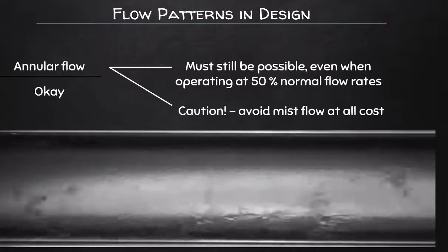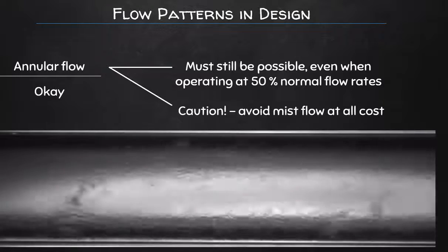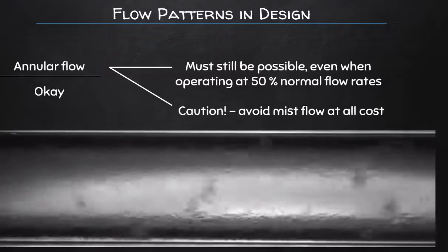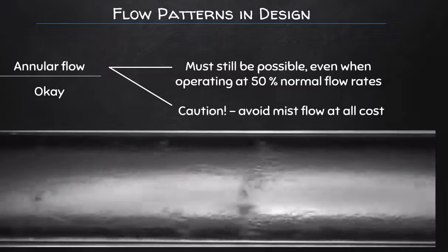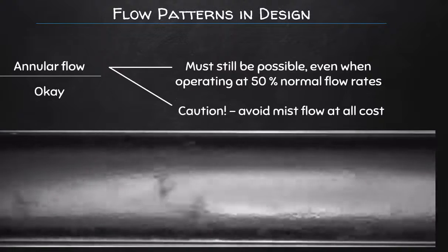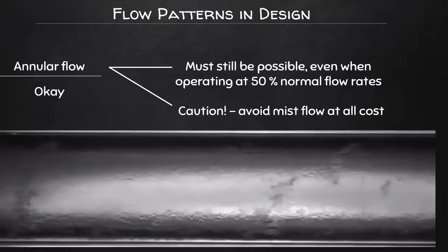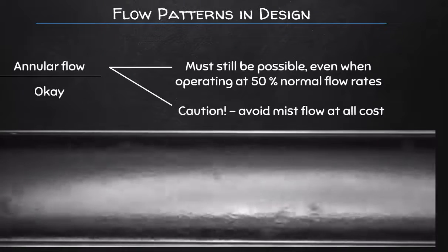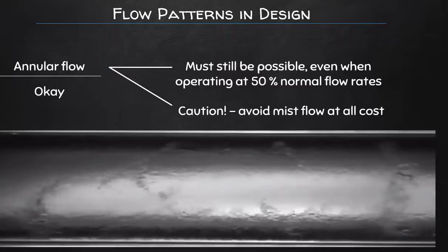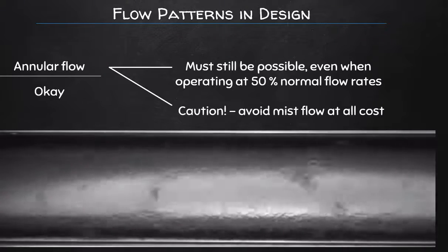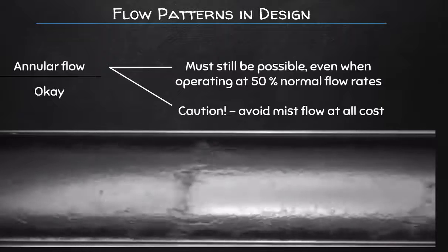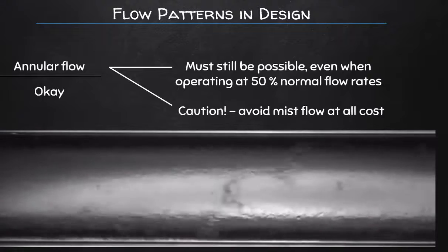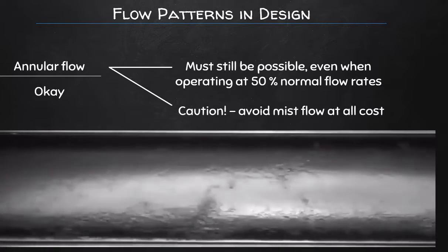So why this is the case is because it is really, really difficult to condense mists once they form. And this is especially difficult if you are working with non-polar organic solvents or organic flows. A good example of this is in my own research area of biofuel synthesis, where we work with pyrolysis oils, which form a type of mist when we try to condense them, and we typically have to make use of an electrostatic precipitator in order to condense the mist to form the oil. Otherwise, we just end up giving it back to the birds and the trees and the environment.